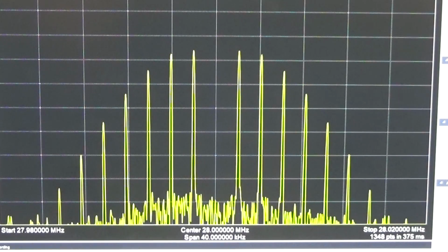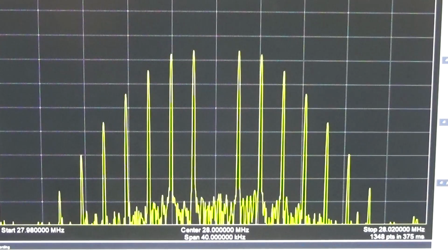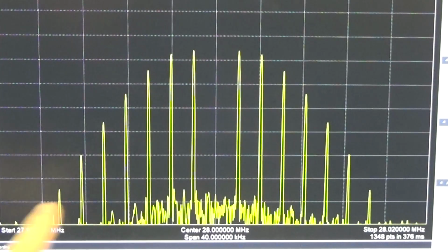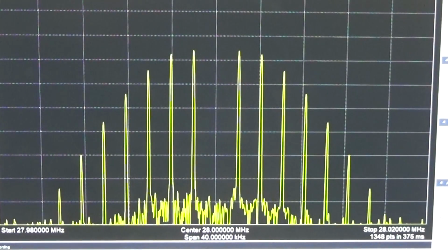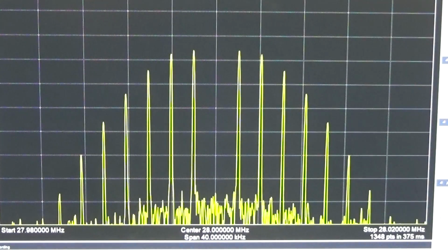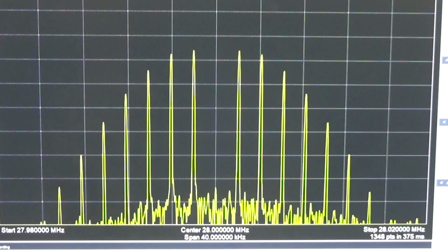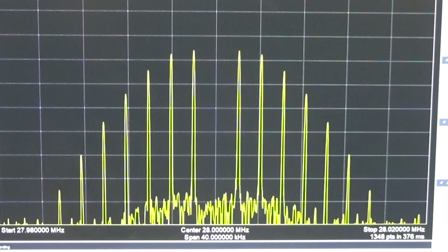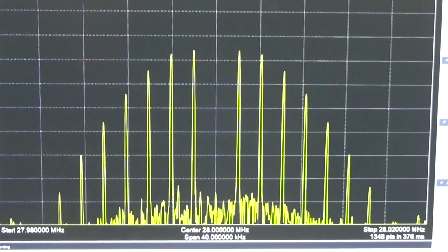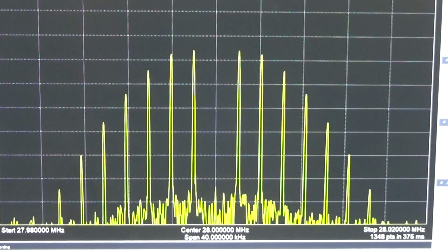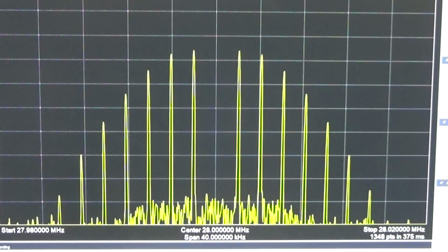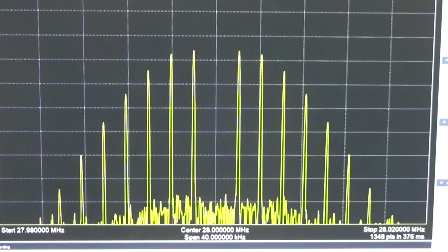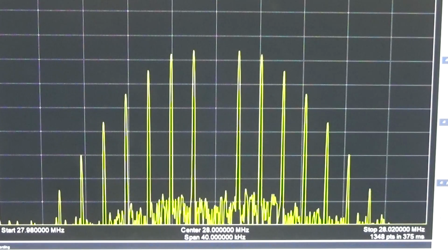So, I'm playing here a little bit with the audio frequency. And now, what you can see here, our fundamental or our carrier frequency has completely vanished. So it is gone. And that means this is now our Bessel 0 point, and that is exactly the audio frequency we need to find our deviation.